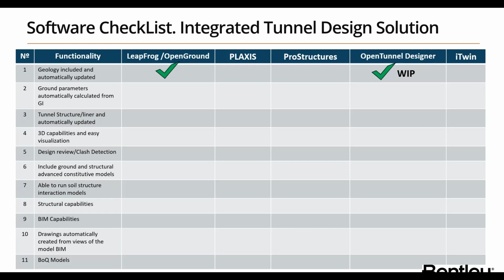So let's say you have your initial design where you have a few boreholes and you start your modeling, but during the design you are receiving new information, and you are just increasing the fidelity of your model. Leapfrog is able to create named versions and automatically update everything.